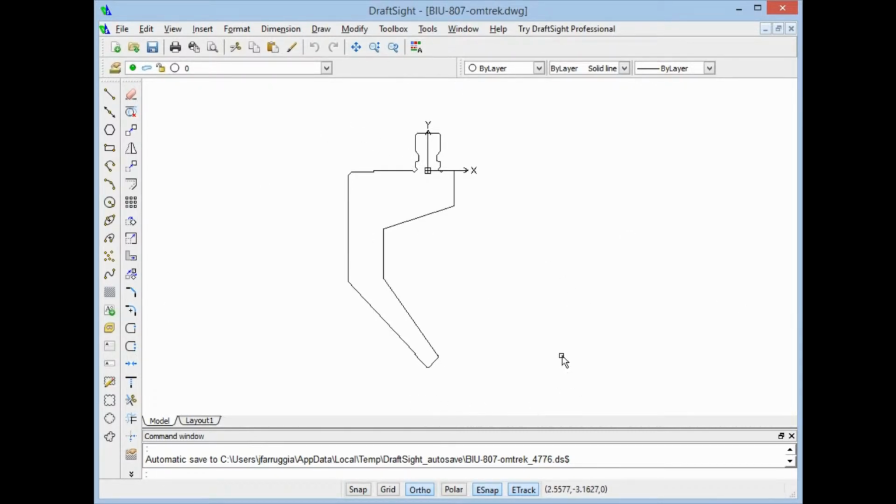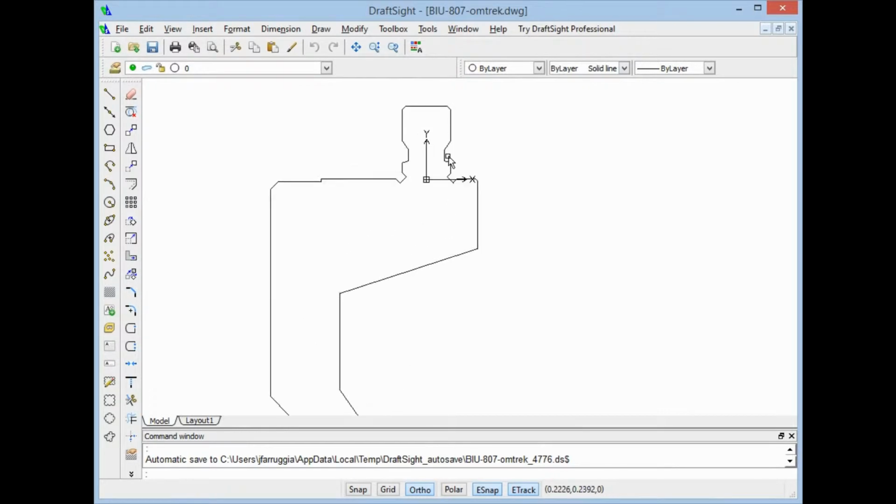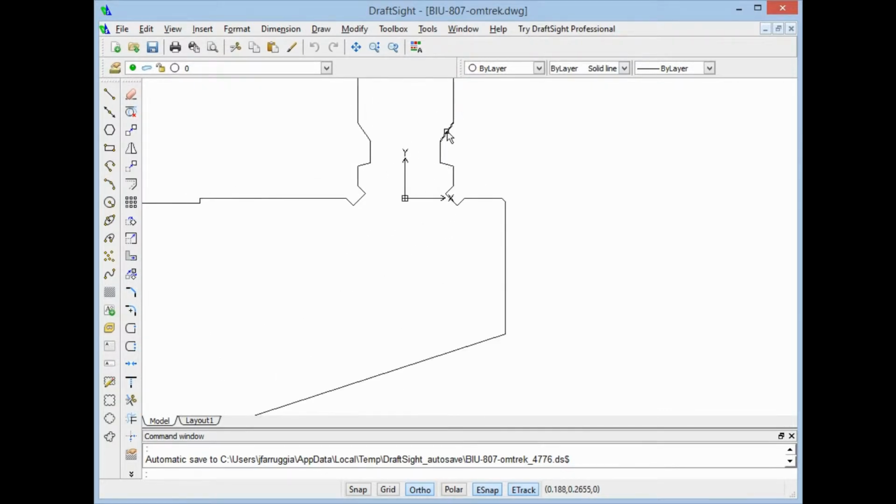This is a very nice method, almost preferred, especially if you can get the drawing from the manufacturer so you know it matches your tool. But the one key thing to note here is that you must have your origin point from the CAD model in between here on the tang. I'll zoom up into here. So in the middle of the tang here, and even with this surface, that's where the origin is on all these American style tools. So be aware of that.